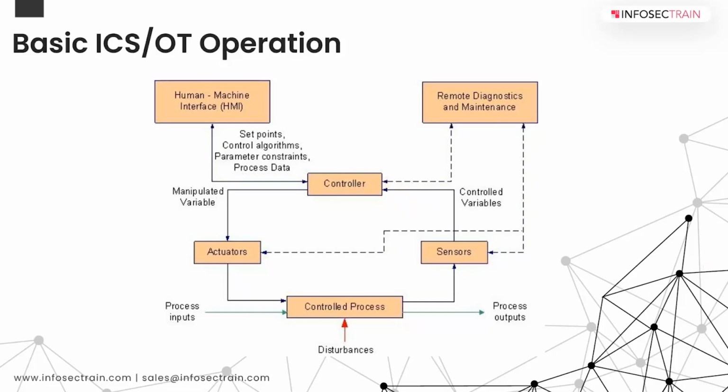Many of today's OT systems evolved from the insertion of IT capabilities into the existing physical systems. I told you, right? Originally, we had electromechanical relays, and they slowly transformed into PLC. For example, embedded digital controls replaced analog mechanical controls in rotating machines and engines. What happened was this improved cost and performance. That was the reason for this evolution, and the result is what we see now.